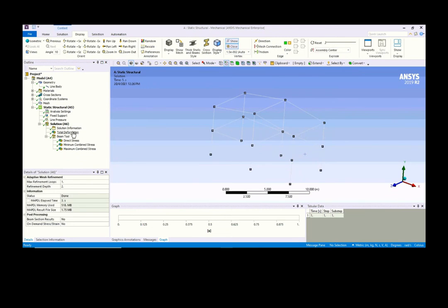You can play around with different meshes and see the difference, because the mesh size is one of the factors I mentioned before that will affect your results. Usually, if you are doing computations, we do a so-called mesh independence test to check what is the suitable mesh size that should be used.